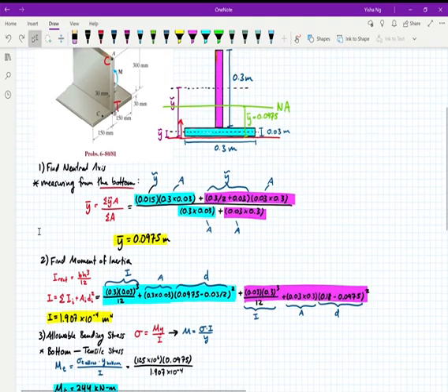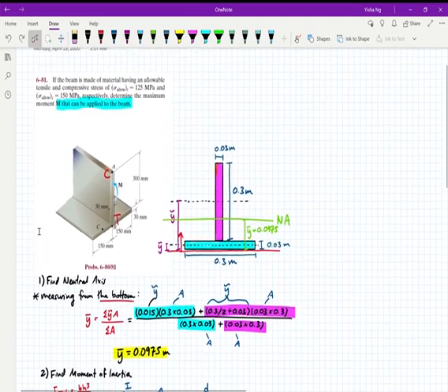The next thing we need to do is figure out where tension is happening and where compression is happening. What you can see in this beam is that you've got this moment which is curving upwards. Basically, the direction that the moment is curving towards, that part of the beam is going to get pressed together and compressed, while the other side of the beam is pulled apart so that it can stretch and get bigger.